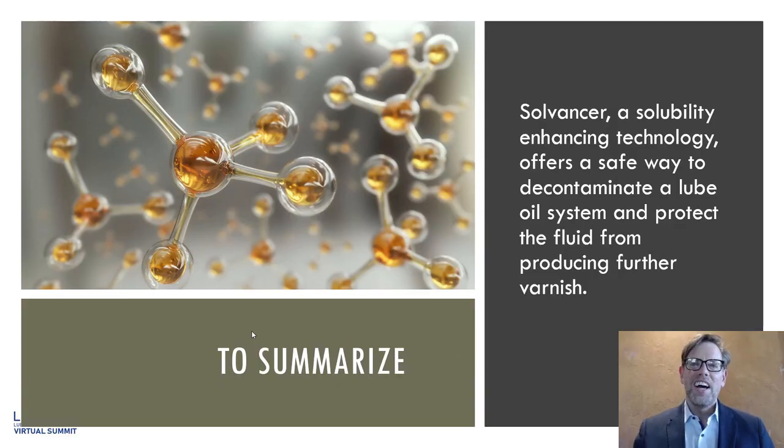And secondly, Solvancer is a solubility enhancing technology. It's a little more scalable than traditional varnish mitigation systems, and in hydraulic oils it can do a really good job of protecting that fluid, improving the deposit control properties of the in-service fluid, and also does a good job of decontaminating the system and dissolving sludge and varnish that has settled in the system.